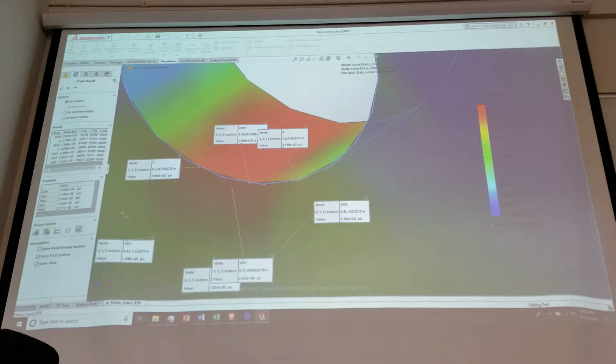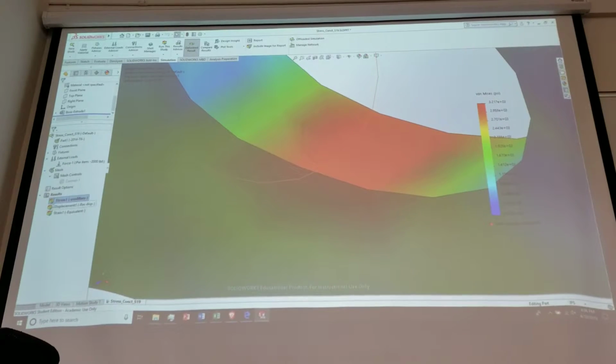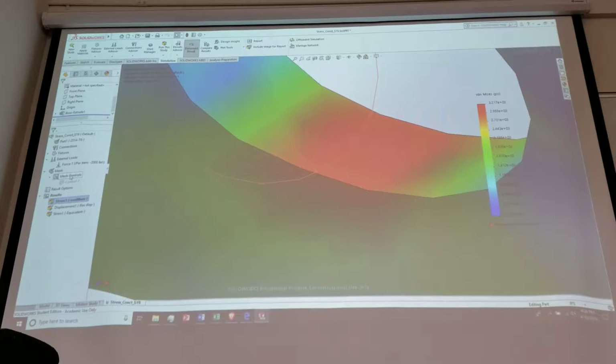And last time, as I had you do this, we went and played with mesh controls, right? Okay. Well, and what do we do with mesh controls? We put finer controls on it, and then we do this convergence study, which we did on the board last time. What do you do? You run it and check one result, and then you run it again and check the result. And while we can do this, it gets to be a bit tedious.